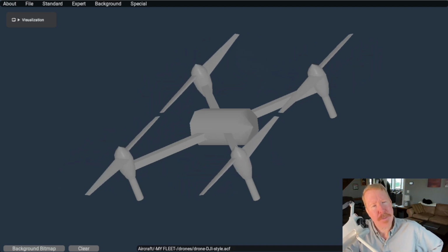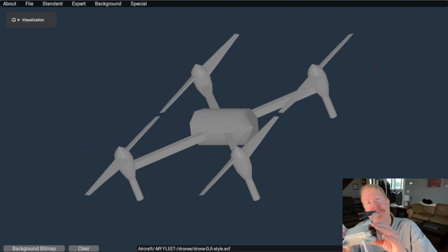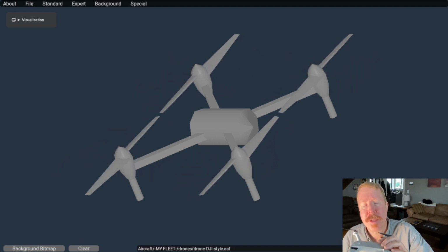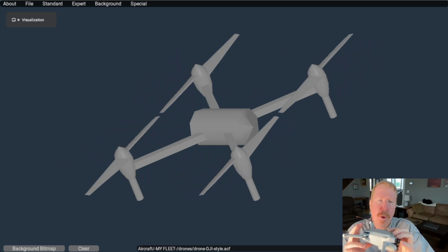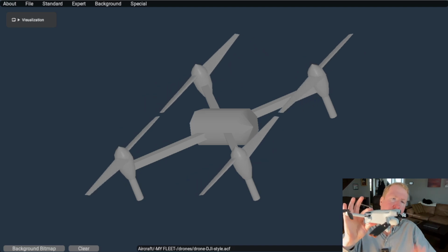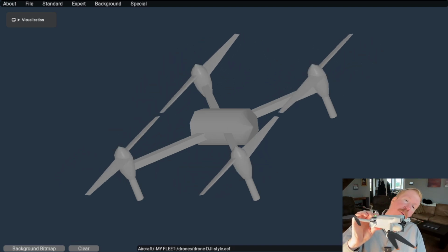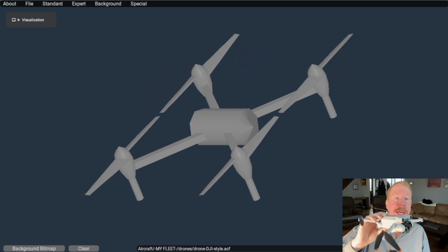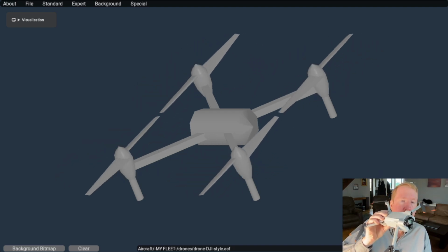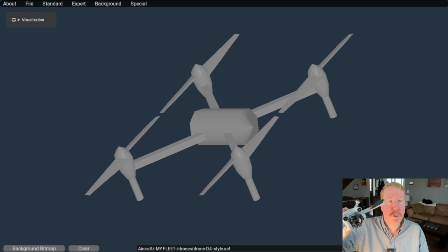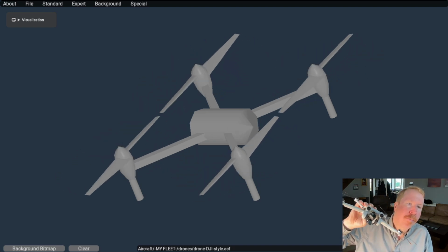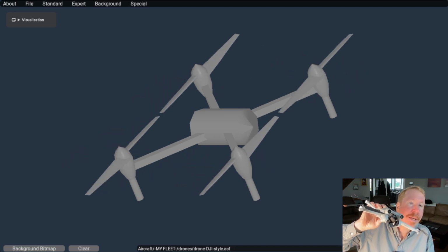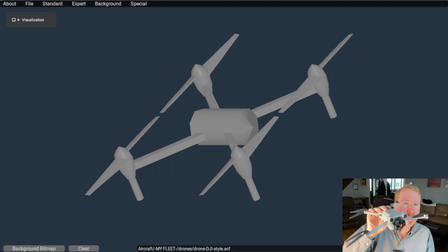What kind of flight control system do you want to have to meet that kind of unique mission of stabilizing at a point in space? And here's the answer. What you really want is, if your hands are off the stick, you want the drone to be absolutely still, just completely motionless. If, on the other hand, you put in full right stick, you want the aircraft to move to the right at a certain speed. Put in full left stick, you want the airplane to move left at a certain speed to get to a new location. Take your hands off the stick, you want to stop right where it is.